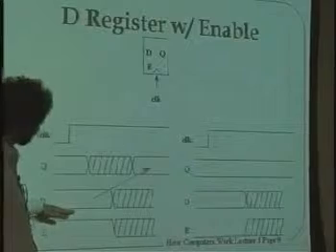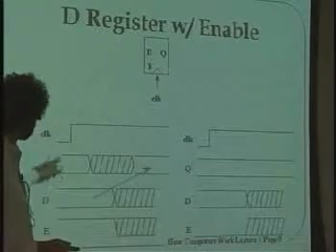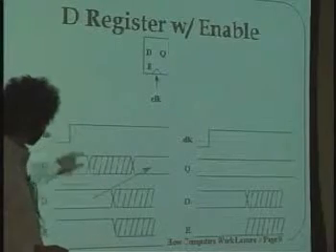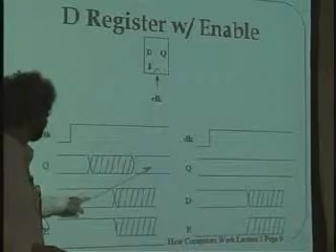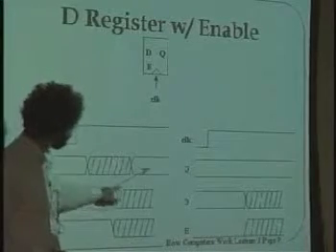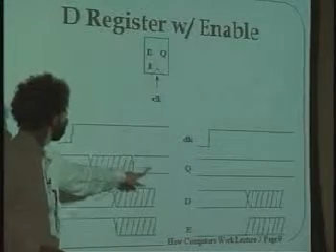It doesn't make much of a difference, except that we know that when the clock goes off, whatever the data value was, a picture will be taken of that, and the result will, after a short time, be put on the output of Q here.